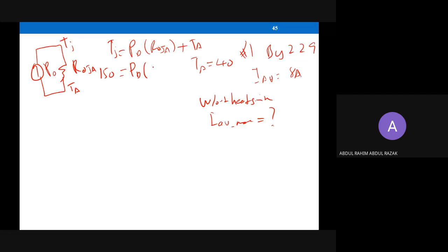R theta JA is also mentioned in the datasheet, on page number 2. A certain datasheet mentions R theta, another mentions R TH. Both can be used. Same goes for degree C: some datasheets mention degree C, meanwhile some mention Kelvin. Both carry the same range, so you can use either.